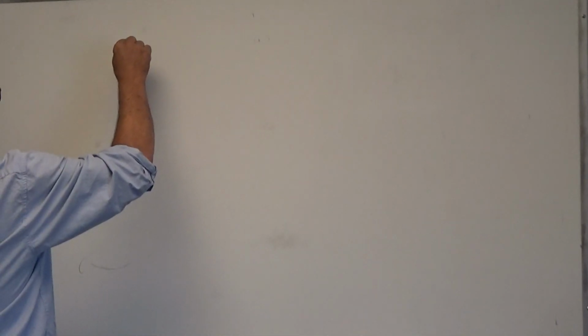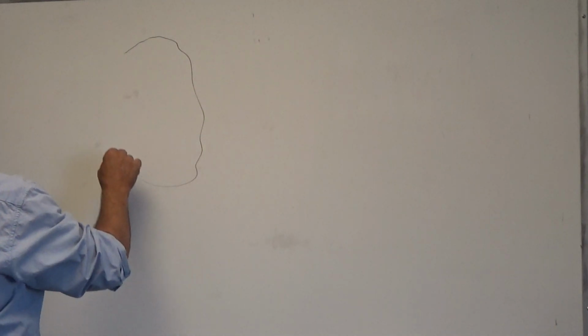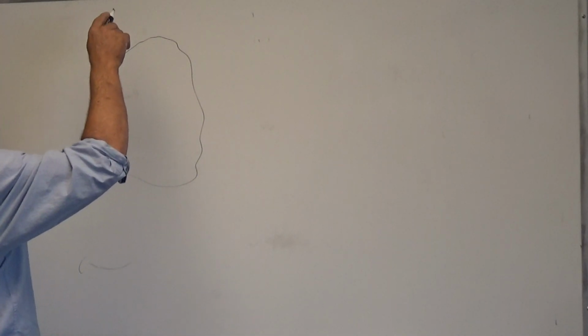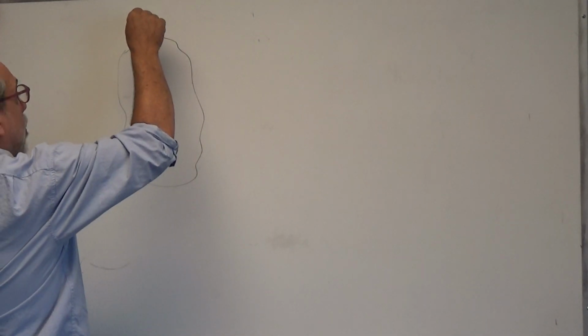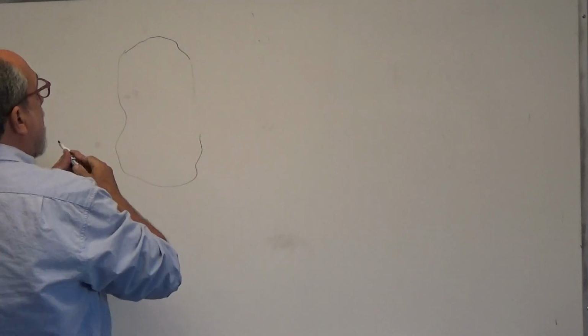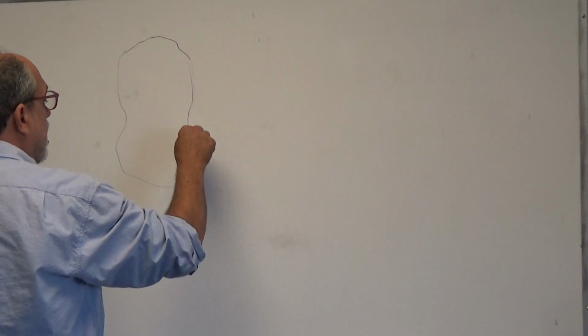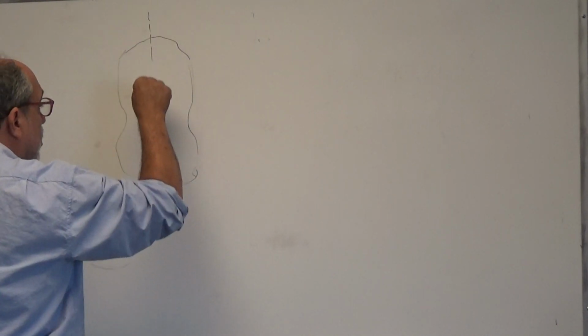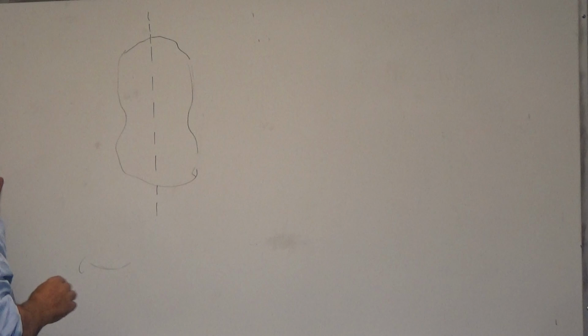Now, without numbers, I want to close by simply saying, if the section was like this, we have to determine the principal axis. And up to this point in the class, the only way that you can calculate the principal axis is in the case where there is at least one axis of symmetry. To be more precise, imagine that I drew this thing and it's symmetrical about this line. So if this is an axis of symmetry, that's a principal axis.